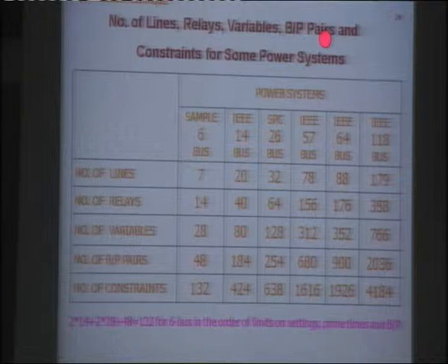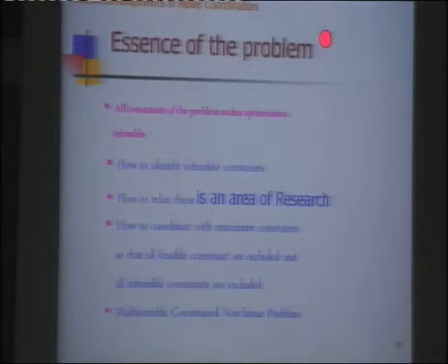So for this location, we see that for a fault near the relay, the primary operating time is TMM. So in this equation, subject to constraints in the pink block, the first equation is TMMI minus TMM greater than or equal to CTI, where TMM means the fault M operating time and TMMI means the backup relay operating time, where I is a set of backup relays. Similarly, the constraint will be for the other side. So all such constraints will be made. And that was only for one pair of relay set.